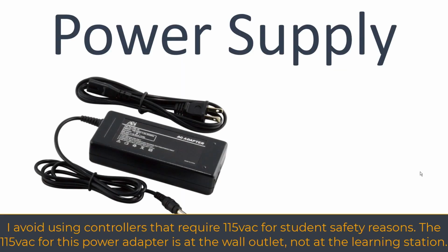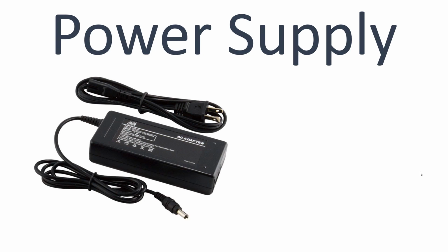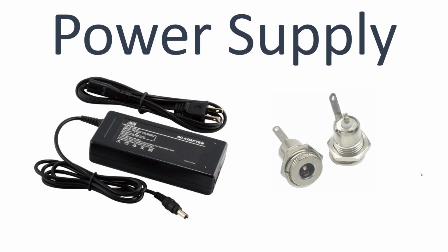Power supply, you can buy a really nice power supply if you want. I prefer to buy these adapters. This is 24 volts DC output at 3 amps. You don't need 3 amps. 1 amp is more than sufficient. These power supplies or power adapters are typically $10 to $12 on either eBay or Amazon.